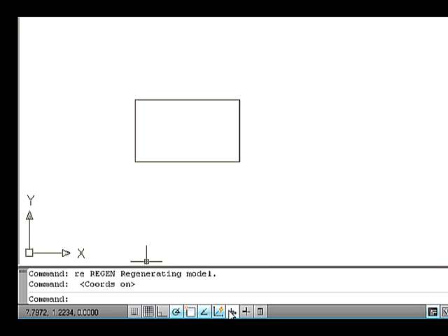Dynamic Input DYN button. Dynamic Input displays commands, options, prompts and user input in a tooltip adjacent to the crosshairs. When dynamic input is enabled, the crosshairs take on some extra features. The coordinates of the current pointer location are always visible at the crosshairs. Values that you type appear in the tooltip, and the dynamic input system displays dimensions when you're drawing things or moving them around. The DYN status bar button controls AutoCAD 2008's dynamic input system. You can toggle off dynamic input by clicking this button.